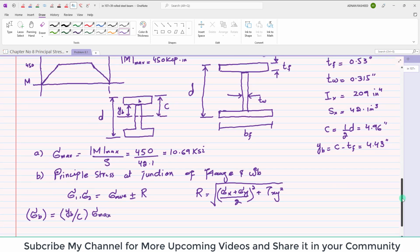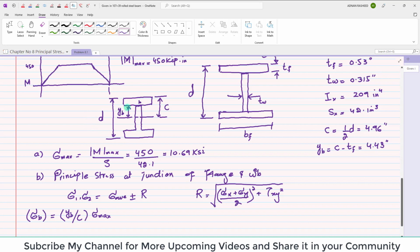You can see YB is this distance divided by C, so the ratio of this distance into the maximum stress that you have calculated. YB is 4.43 and C is 4.96, times 10.69, which will give you the value of 9.55 ksi.